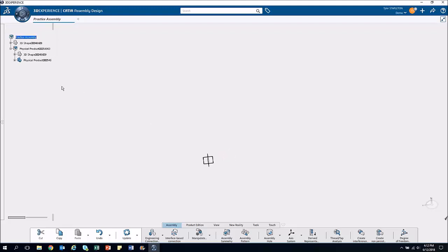Alright, so let's talk about what I just did there. We have three different types of objects up here: an assembly, a 3D shape, and a 3D part. These are just designations that help me deal with the items I have saved in the tree, as well as help me save these as parts within my collaborative space. An assembly is a pretty straightforward thing. It's essentially a collection of parts. Into an assembly, I can add sub-assemblies and parts. I could add a part directly into this assembly instead of inserting one into this specific sub-assembly, and also 3D shapes.